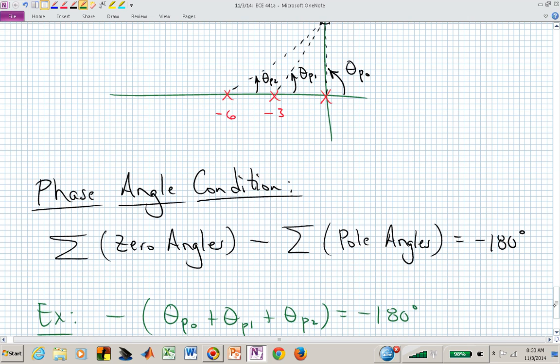Have we already talked, though, this semester about finding roots on the imaginary axis? Do you remember doing something, an array, somebody's name in an array that allowed us to find imaginary axis crossing. So there's many different ways to do this. We're trying to find where do the closed loop poles cross the imaginary axis? Well, the Routh array gives us that also.